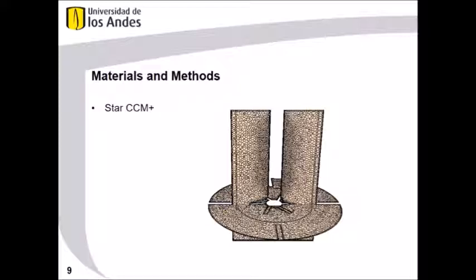Finally, the number of cells was 429,000 for the pitched turbine. This number is part of the range established in the statement of the project. On the other hand, 499,000 cells were obtained by meshing the Rushton turbine, which is an ideal number compared with the recommendation previously mentioned. In addition, it was not necessary to change the initial mesh conditions.